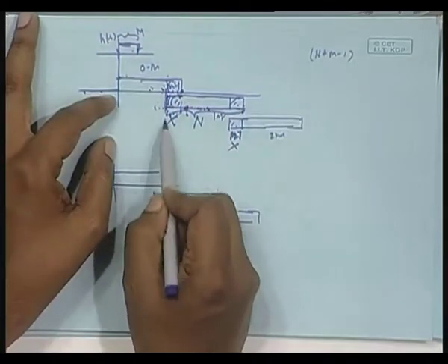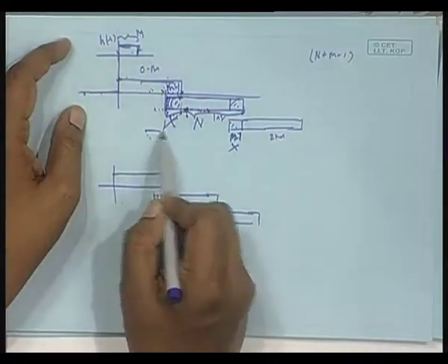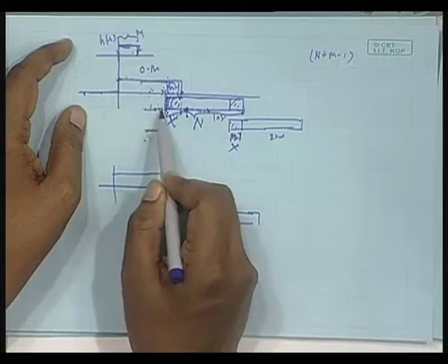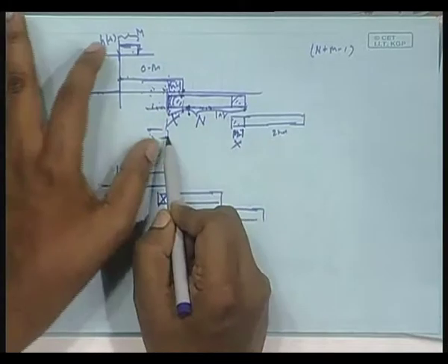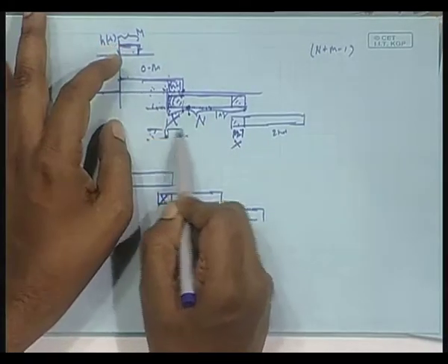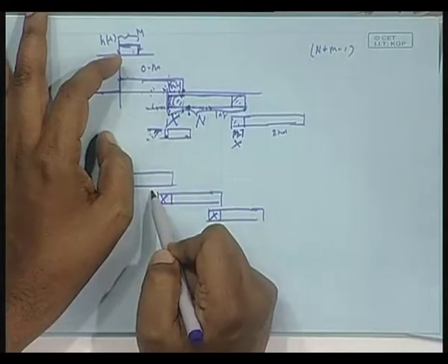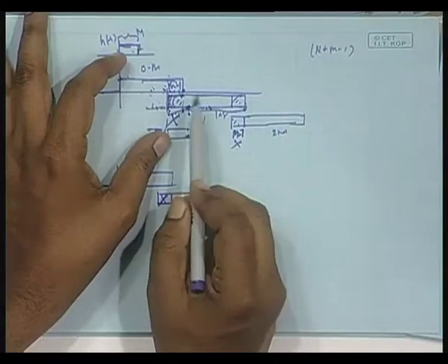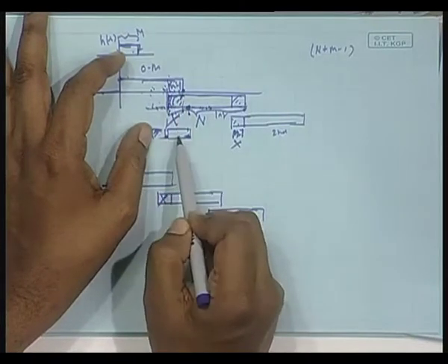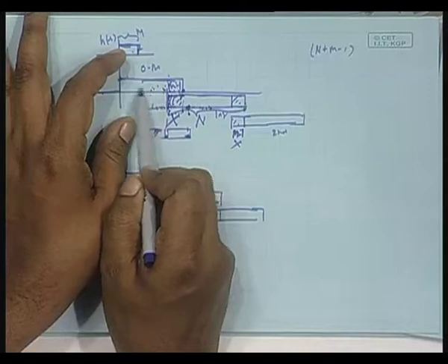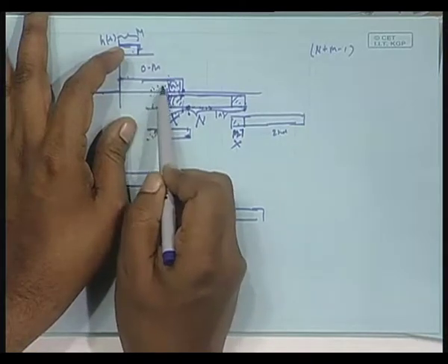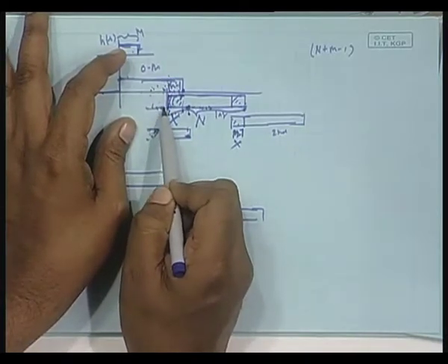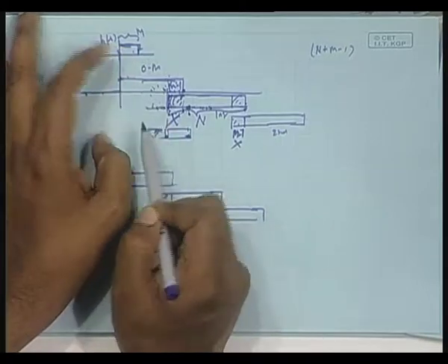Suppose this is the origin, you first reverse it, all zeros are coming, because on this side there are zeros, so incorrect result, but as you move it here, from this point onwards, you need purely linear convolution, and the linear convolution between this and this is enough. I do not need any data from here. You can say that look, originally there was some data and now you have got zeros only, so you are getting incorrect result, but that does not apply here.